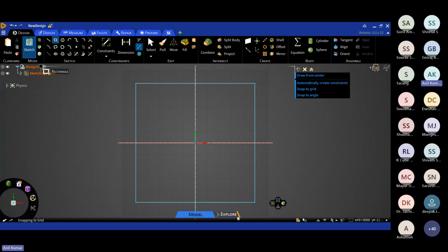So those kinds of capabilities are there in the Discovery tool itself. And if you talk about modal analysis, only up to 12 mode shapes we can extract in Discovery. So this is the limitation. And of course, dynamic analysis like harmonic analysis and all that, these capabilities are not there in this Discovery tool.